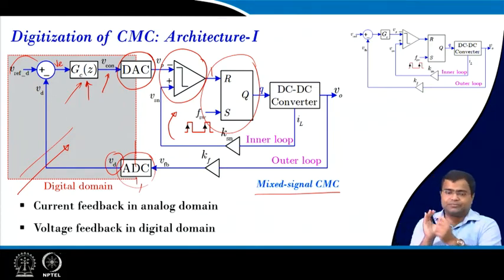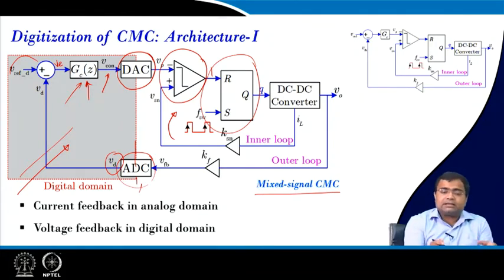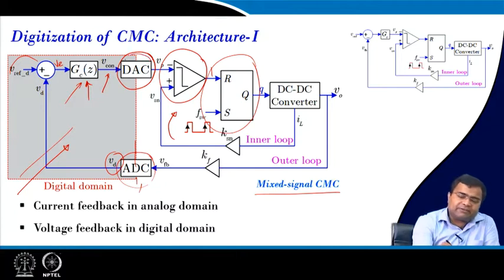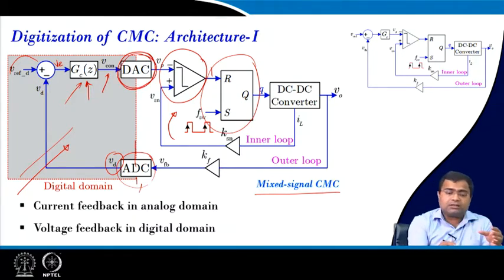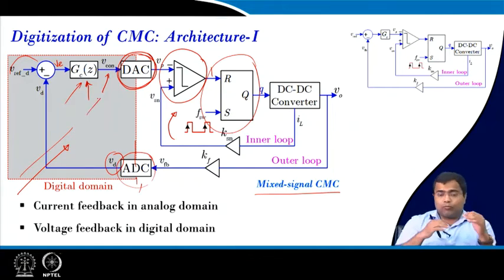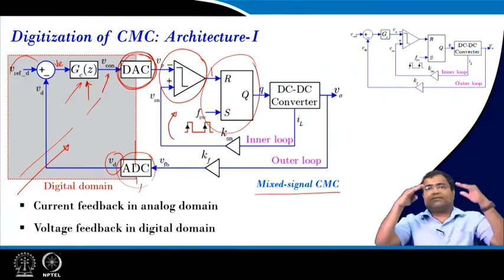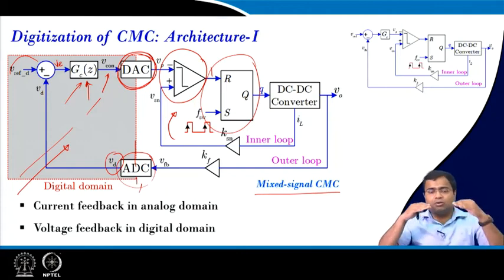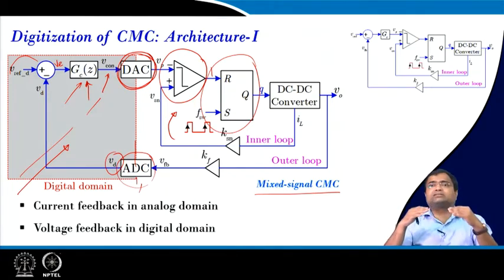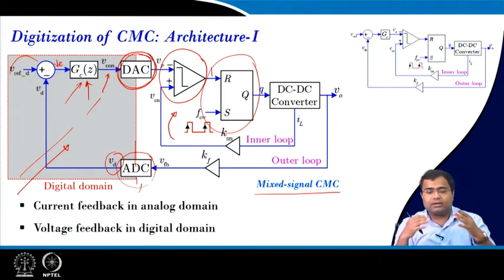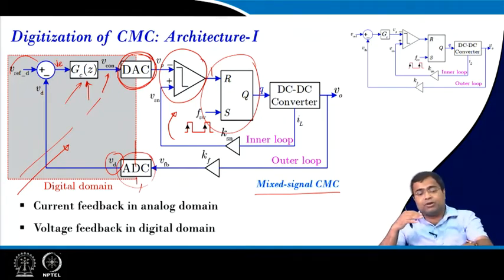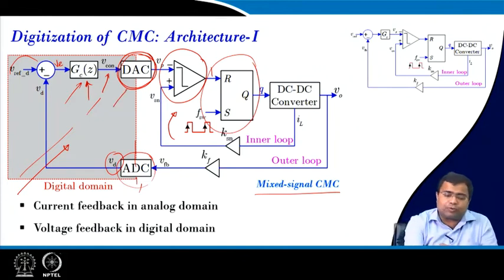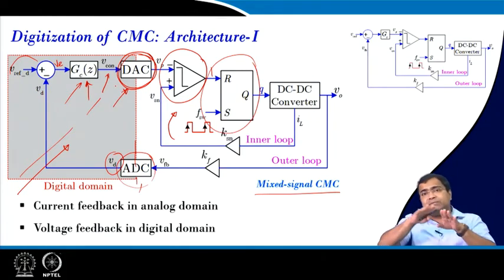That is another possibility. The third possibility, since we are generating the reference current from inside of the digital controller, that means this whole in digital, we can always use a programmable current reference, because in peak current mode control we should be able to protect the circuit. That means if you want to protect, we want to program the current reference either higher or lower value, because if we use a program current value from the digital domain, then it will limit the actual inductor current.